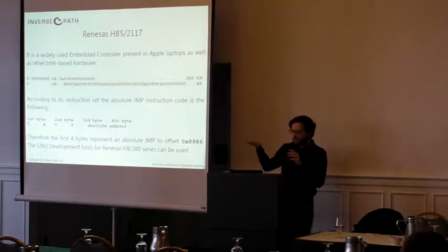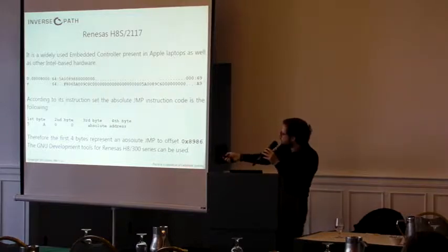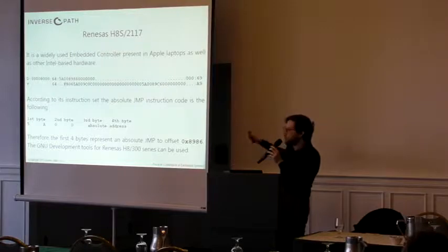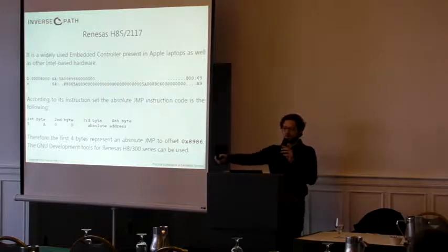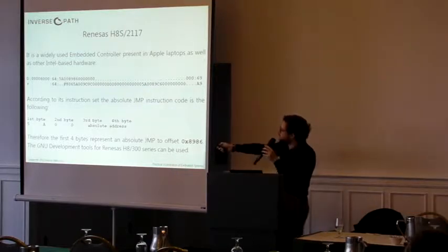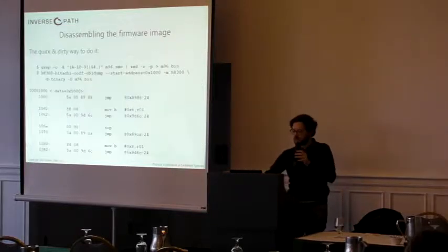And according to the instruction set, the first thing that we see in the actual firmware image is compliant to a jump instruction, which actually makes sense, that your firmware would start with a relative jump to somewhere in the code, bypassing all the different knobs that are here. So it makes perfect sense, and you can find the development tools for it.